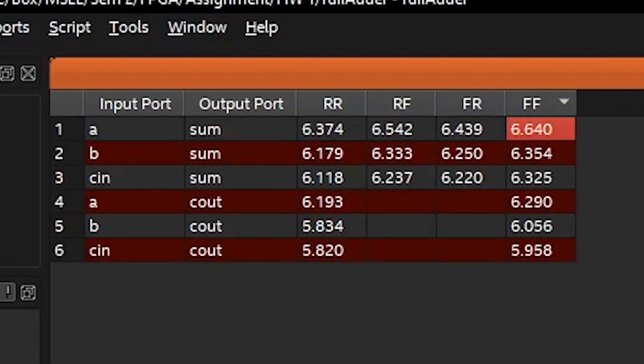Since for this experiment we haven't provided any timing constraints or layout constraints, the application will randomly select how the logical blocks are placed. Due to that randomness, we can see either A, B, or C in ending up in sum being the longest path. In my case, it happened to be A to sum. For others, it can be B to sum or C in to sum.